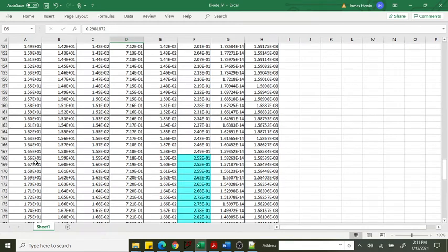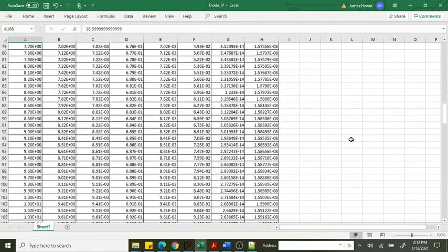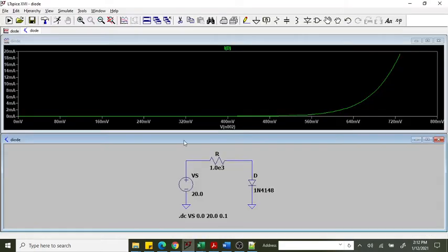16 and a half volts on your source, because then you start dissipating a lot more power, and this gets above a quarter of a watt. So that's just something to be mindful of when you're doing a simulation in LTspice. You can do that, but if you're really doing this on the breadboard with real components, you've got to be mindful of the power rating and how much current the circuit is going to draw. So that's something to be aware of.